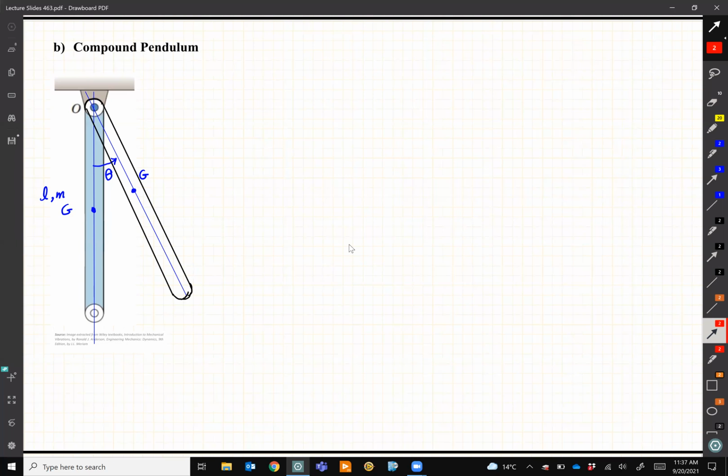Okay, wherever you are, I'm sure you are on the right track, but let's quickly solve it together and move on to the next example of the section. So the system, we know how it moves. The free body diagram, because I have the center of mass, simply has mg. Definitely we need to include weight because there is no spring here. And O is a fixed point, so we don't need to worry about that, but just to include it in the free body diagram, I have the Ox and Oy.